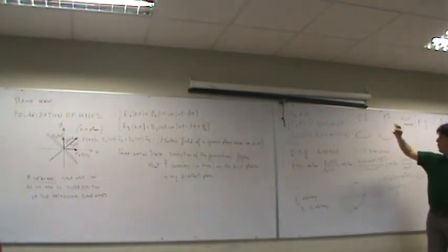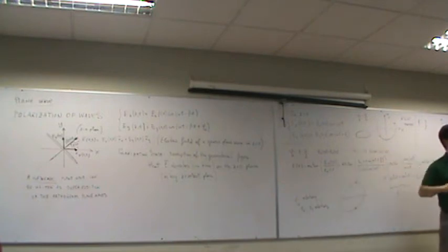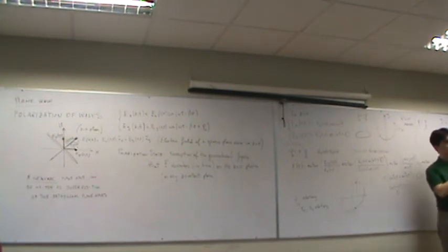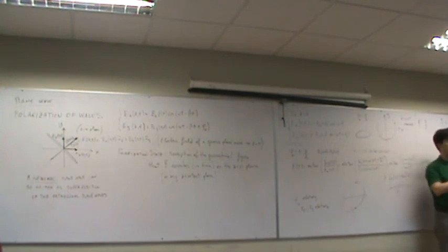And if you use horizontal and vertical polarization, this shape has no impact, it does not change your polarization state. And since you use horizontal and vertical polarization to carry two independent fluxes of information, that is, you make frequency reuse, this choice for the polarization does not mix up the two electromagnetic fields.